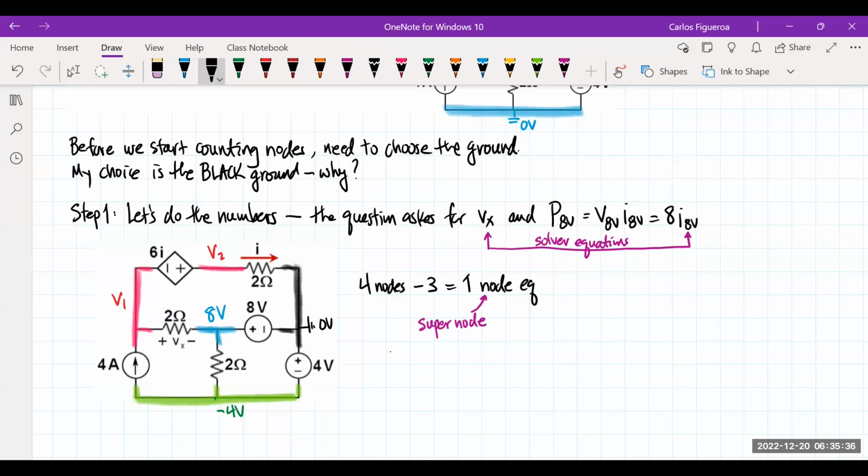So then if I start the counting here, I have my supernode between 1 and 2. So that means I'm going to come in here. I'm going to do this. So my supernode goes like this. There's my supernode right there. Then, of course, I have a supernode condition. And then when I look at my DC, I said my DC here is going to be I here, because that's what the source did. Let's look at this thing a little bit more carefully here.